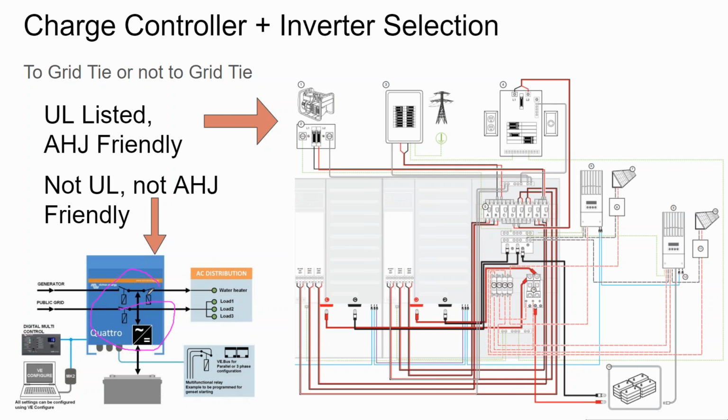And then you're spending almost as much money on an external transfer switch as you are on these battery inverters that already have that switching functionality built into them. So that's where you might run into some instances where you get the disconnects and the transfer switches built into your battery inverter, but your local jurisdiction might have some other interpretations on some additional balance of system material you need to get.